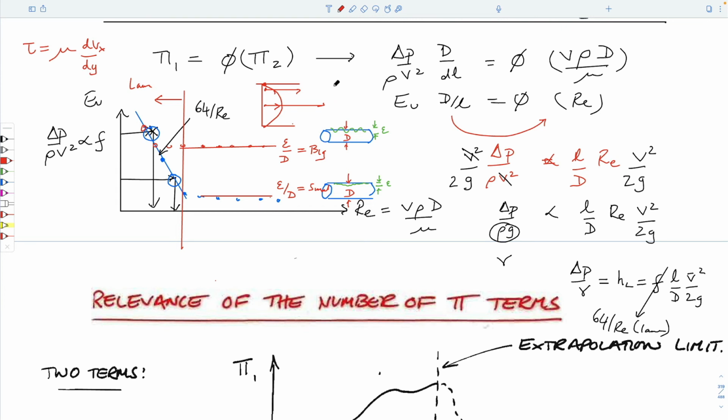If it's turbulent, then the behavior you get across the pipe is that this velocity here might take some detours. And so it turns out that the profile for fully developed turbulent flow is much closer to a uniform flow, because all the single particles are doing this random walk type thing. And so if you look at the macro scale, they all seem to be moving in general at the same rate right across the pipe. In laminar flow, the essence of laminar flow is it's zero velocity at the wall of the pipe, and it's a maximum velocity in the middle. And so we wouldn't get this behavior otherwise. So that's it.